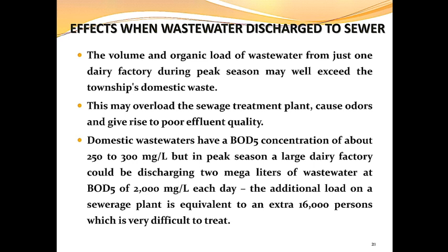A sewer is a pipeline or underground conduit used for the transportation of sewage to the sewage treatment plant. If we discharge dairy industry wastewater into the sewer, it may overload the sewage treatment plant and change the effluent quality, causing odor problems and poor quality effluent.